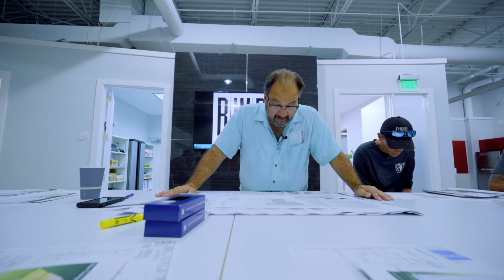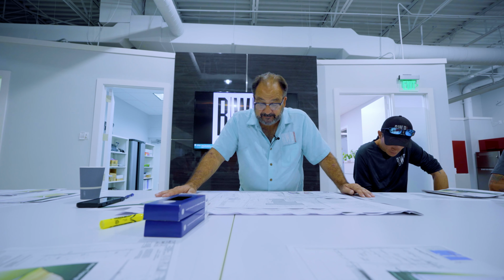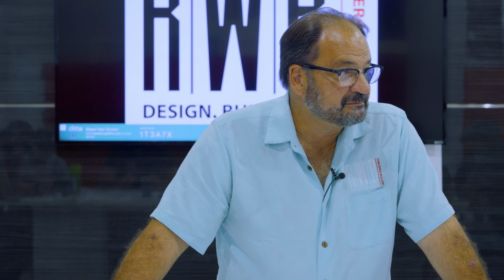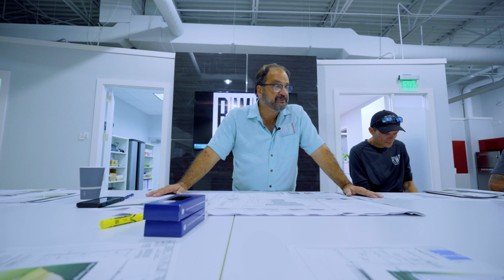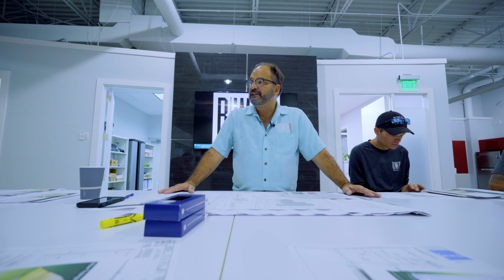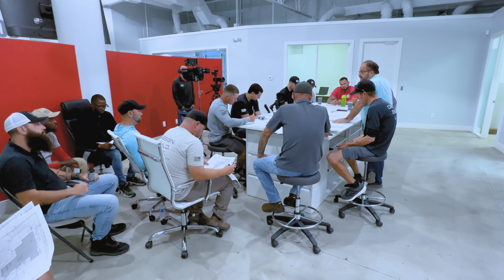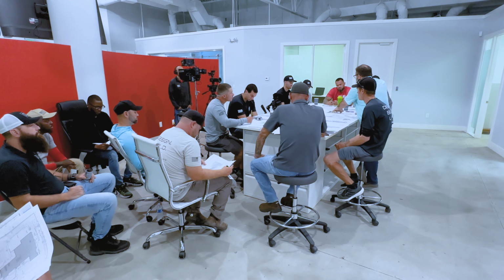Okay. Now that top of wall is 20. If you look on the other one, top of wall is 25 on the existing wall. That wall becomes irrelevant. You don't need it for that part of it. So you have to go through these plans ahead of time. You have to understand what they mean. You have to basically picture the contours just like this.